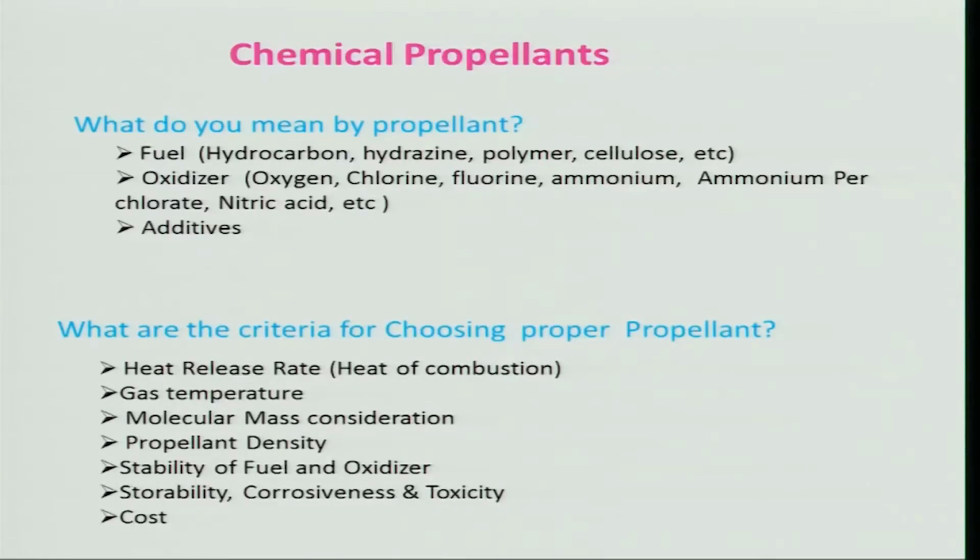And propellant density should be much higher, so that it will be compact. It is valid for liquid fuel and solid fuel, particularly for solid fuel, because the storage space is very important. If the density is higher, it will be compact in the same volume, the mass will be higher, and the chamber volume of the liquid propellant will be reduced if you are using a higher density propellant. Therefore, it is very important.